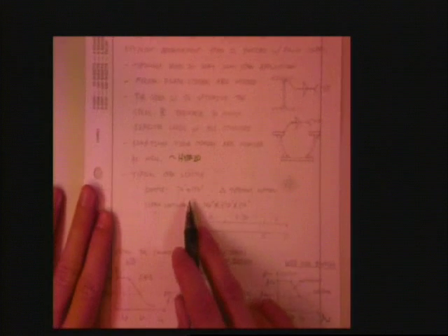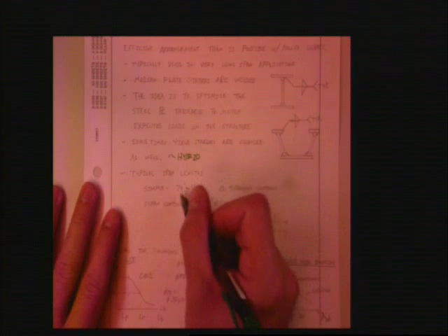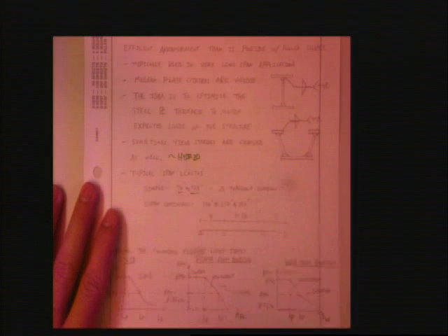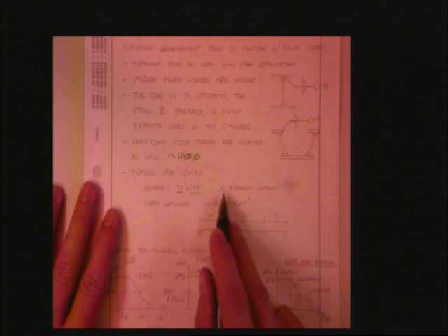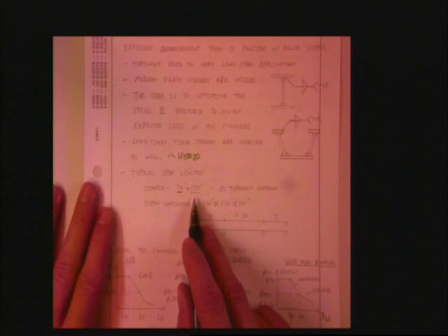Typical span lengths. If you get to something like a 70-foot to a 150-foot span, deflection is going to control. Plate girders are usually the way that you go. It starts to get real hard to do a 70-foot span with the rolled section. It can be done, but it gets hard, especially if you have depth restrictions. Things like that.